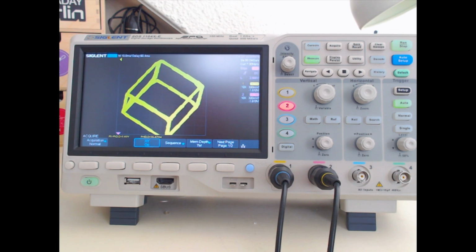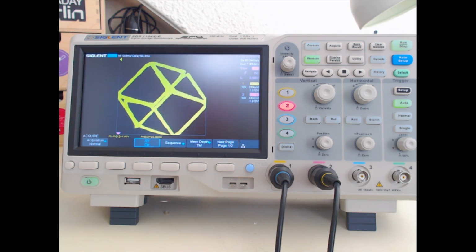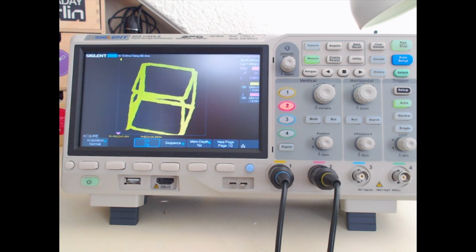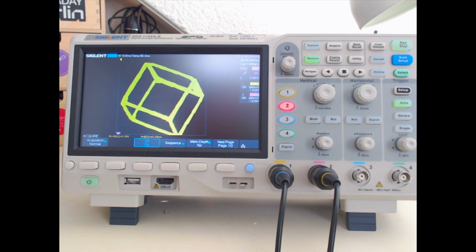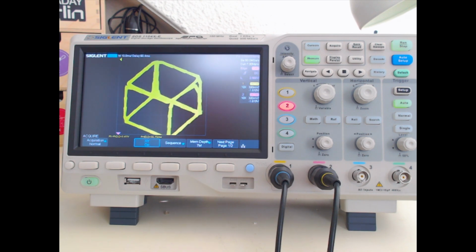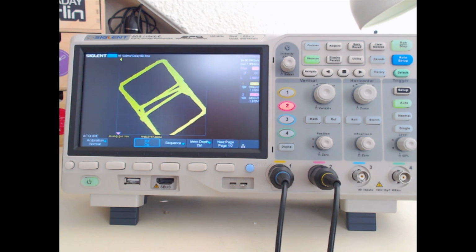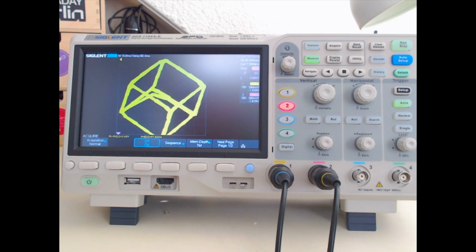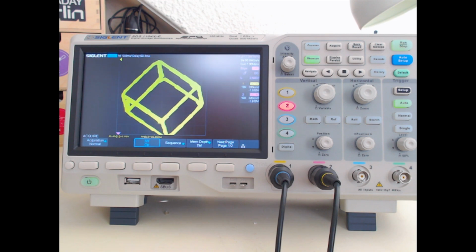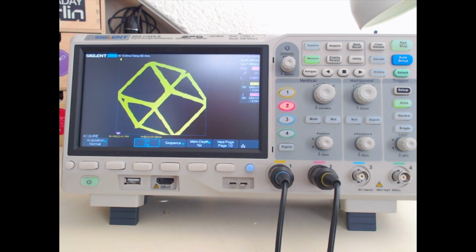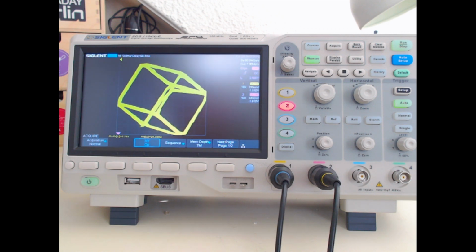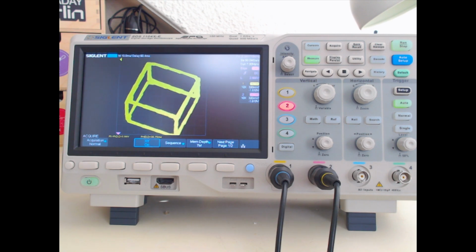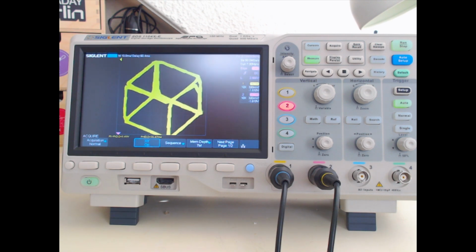One of the coolest things about this whole demo, and I'll show you the electronics in a minute, is that it's literally just a microcontroller and 4 passive components, 2 resistors and 2 capacitors. So if you already have those things around, and of course if you've got a scope, which is probably the hardest thing to get access to in this whole setup for the hobbyist, you can 100% do this already, probably today.